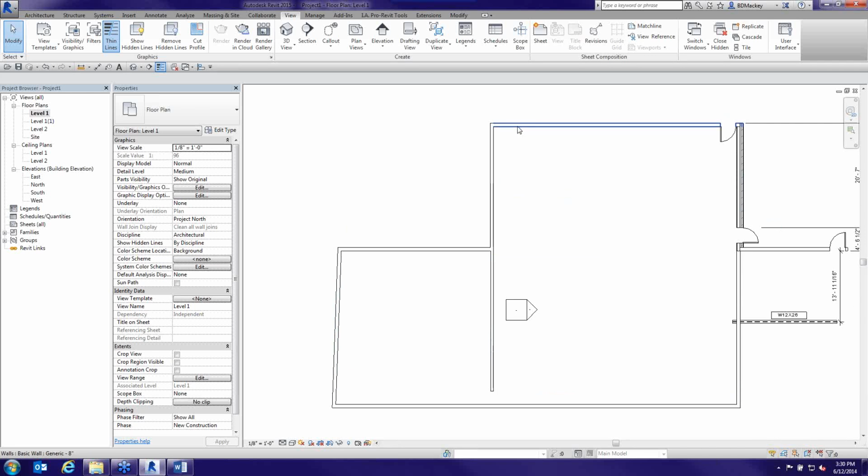What I was going to show you is that it depends on which side of the object you tab on. If I hover over the inside, a lot of times I've had this scenario where Revit will grab this inside wall, but you're like, no, I wanted to grab all the exterior walls. What I've found, especially in a scenario like this, you can see tabbing multiple times will get me into it. But if you're hovered on the inside of an object as opposed to the outside of an object, you can get two totally different tabbed scenarios.